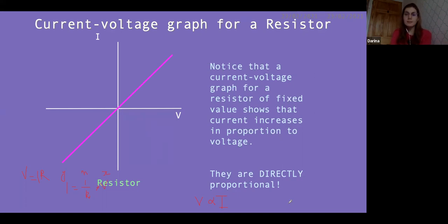Ohm's law only works under a constant temperature, which produces a constant resistance. So ohmic resistors, think just normal square resistors that you've used in your circuit diagrams. For something like a filament light bulb, which we just covered, do you think the light bulb is an ohmic resistor? Yes or no? We've got a lot of no's, and that is the correct answer. The light bulb is a non-ohmic resistor because there is a temperature change there. Ohm's law and this graph only work for a constant temperature.